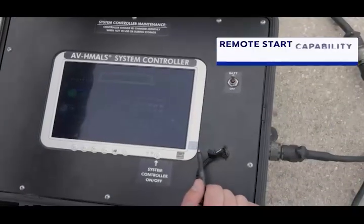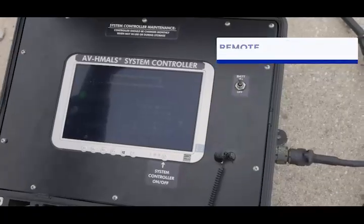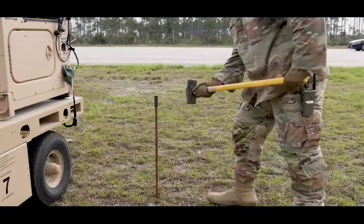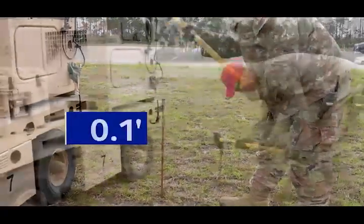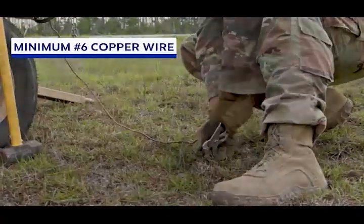The generator has remote start capability, activated using the wired controller. The remote start controller is located on top of the generator. For grounding, drive the ground rod within 5 feet of the generator using a minimum number 6 copper ground wire.